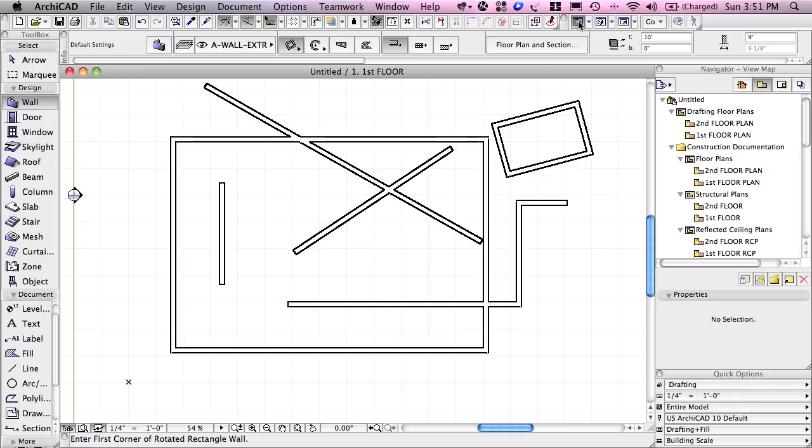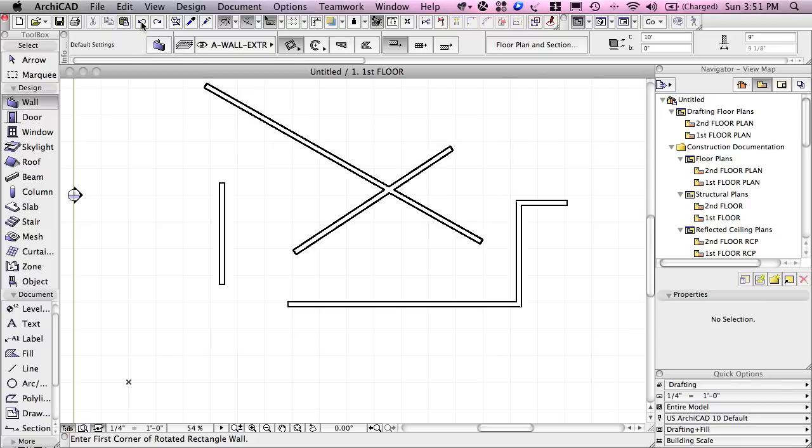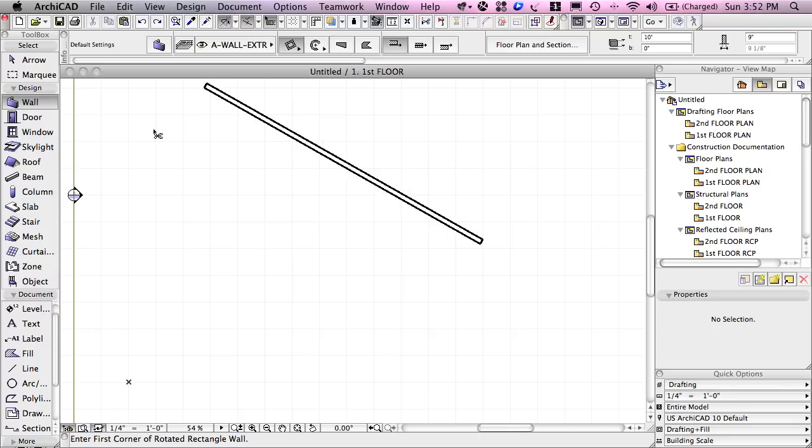So moving on, I don't really want to start with this mess. I really would like to go back and undo what I did. So you'll see there's a little icon button here that says Undo Wall. And in fact, it undid the group of walls. I'll click it again, and it undoes the box of walls. And I can keep going, and you'll notice that as I hover over this, it says Command Z is the shortcut. On Windows, it would be Control Z. So you hold down the shortcut key, Command or Control, and type the Z, and you can see I'm backing up step by step until, in this case, there's nothing left.